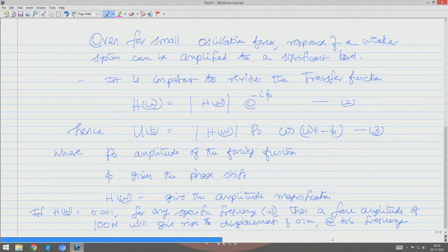We also have to recollect that the transfer function or the impulse response function is not load dependent, but is system dependent. We would like to connect H omega closely with the dynamic amplification factor in the consecutive sections of this derivation.